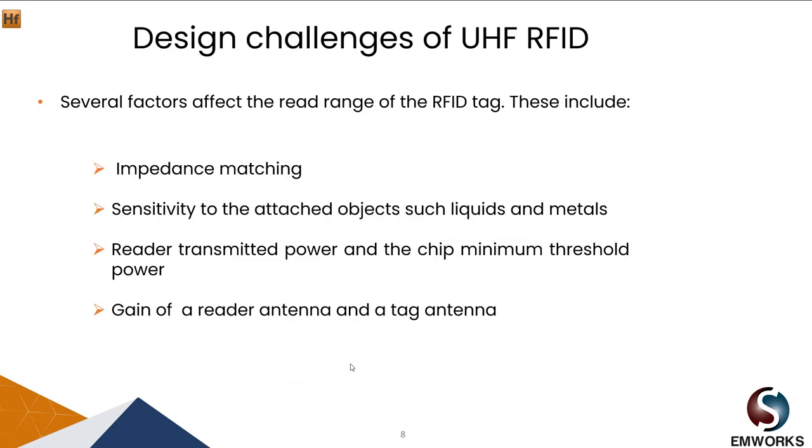Alright, so now let's talk about some design challenges of UHF RFID. There are several factors that degrade the RFID performance, mainly the read range. These include the impedance matching between the tag antenna and the chip, also the sensitivity to some objects such as liquids and metals, as well as dielectric materials.